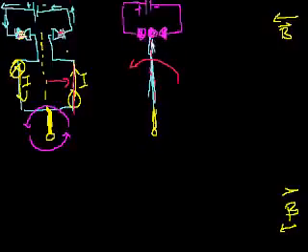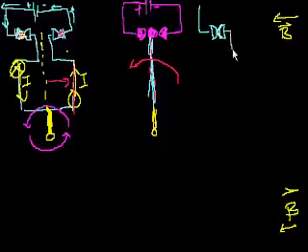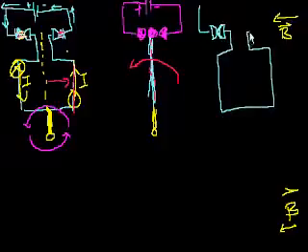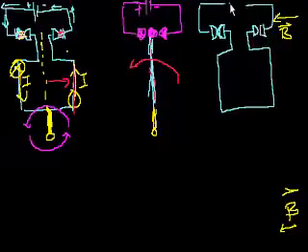So you have no circuit flowing, so you save a little battery energy, and you just let a little bit of the angular momentum carry this whole rotating contraption further a little bit, to the point that your configuration will look like this. I know I keep changing colors, but the whole contraption will now look like this. Okay, that's my positive, negative, positive, negative. Current flows like this. Now, we assume that the commutator has gotten back in touch.